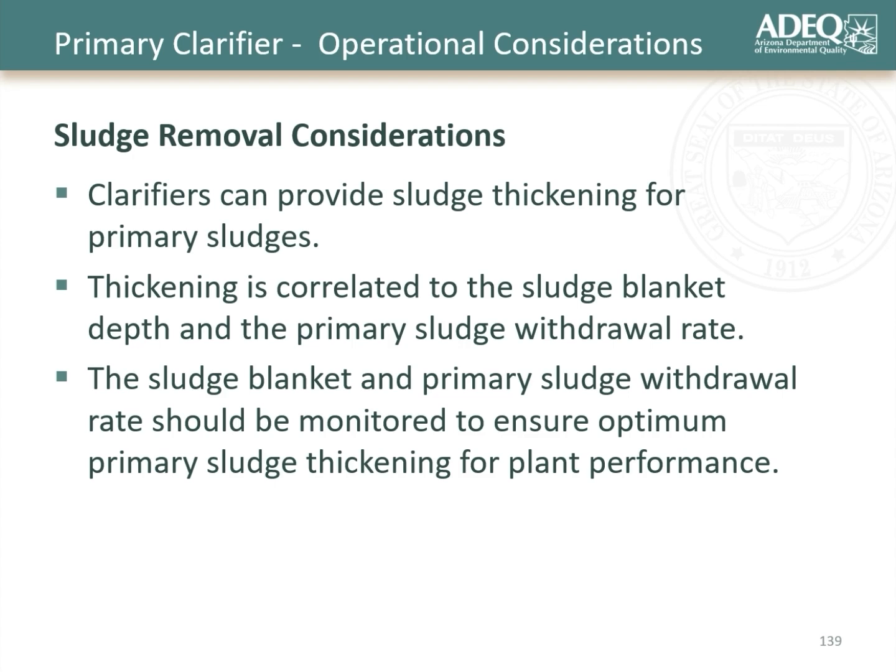So ultimately, think about your plant to get optimal performance as well, because after your sludge is withdrawn, however the sludge is being handled in your wastewater treatment process after the primary clarifiers may have a particular design concentration it was assumed to be. And if you're too thin or too thick in terms of sludge concentration, that can impact the performance of whatever the primary sludge is being handled with, whether another thickener or being added to some kind of digestion system.